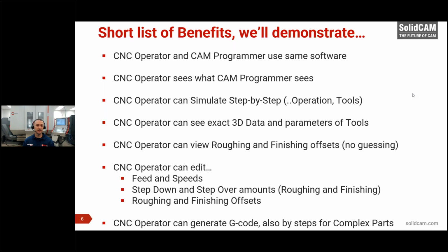As the operator, we get to see the exact 3D data and parameters of the tools. Let's be honest, coming from a machine shop, one of the biggest things is tool setups. In today's environment, where tools are getting more complex, especially mill turn with all the crazy holders and this and that, being able to see the exact 3D representation of the tools is huge.